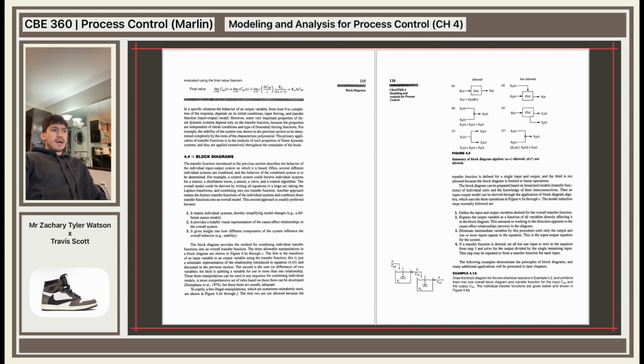So instead of compiling the equations prior to taking the Laplace transform, you have the transfer functions distinctly labeled or identified, and then you combine the transfer functions into an overall model. And usually you just multiply them if they're in a series. So the second approach, which has individual transfer functions combined, is what we have been studying extensively.